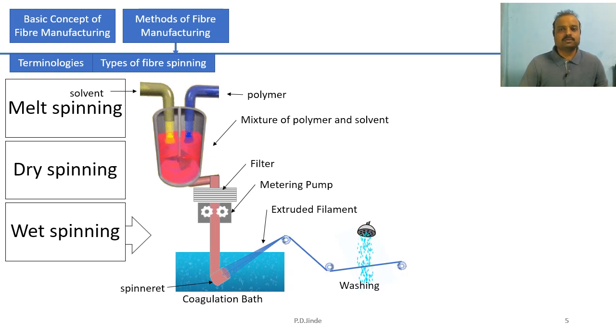The process of passing a polymeric solution through a small hole is known as extrusion. The extruded polymer solution is called extrudates. Solidification takes place when extrudates come in contact with chemicals present in the coagulating bath. Here, this solidification is the result of interchanging the solvent with the chemical present in the coagulating bath.